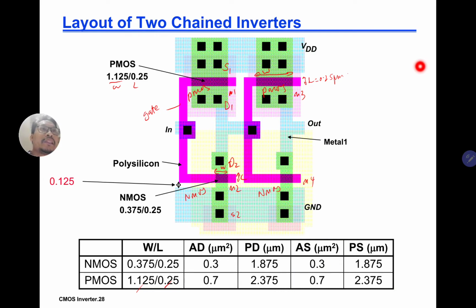How big you want to design your transistors, your W and your L. That one you can control, and we've analyzed already. The sizes will impact your VTC, your noise margins, and your speed. Basically, it's the main parameter that we as designers can control.